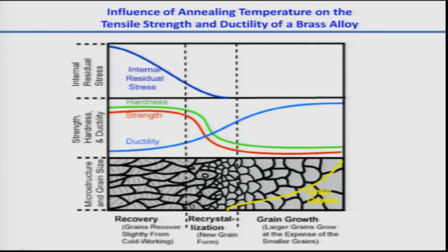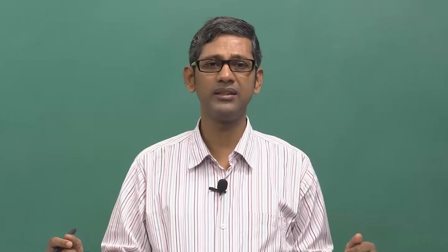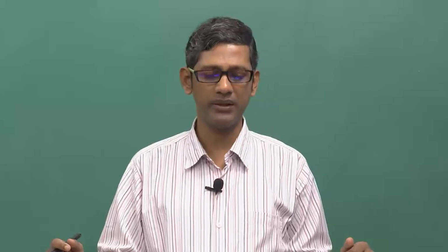Internal stress is basically stored in terms of deformation energy like dislocations, point defects. This energy which is stored in the material needs to be removed, then only the material will regain its ductility, plasticity or change its material properties.